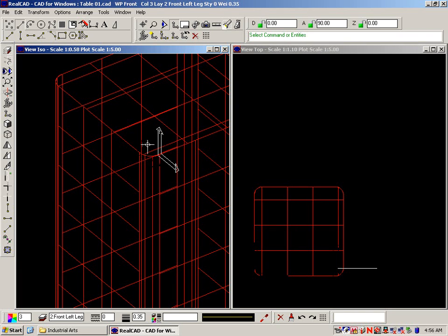But that front corner is not where I want to draw my mortise. I want to have my work plane starting 5mm in. So again, change work plane origin, but this time I'm going to use coordinates, and the coordinates display at the top of the screen here. And to get those coordinates in the right place, I want my x to be the same, so I type x0.